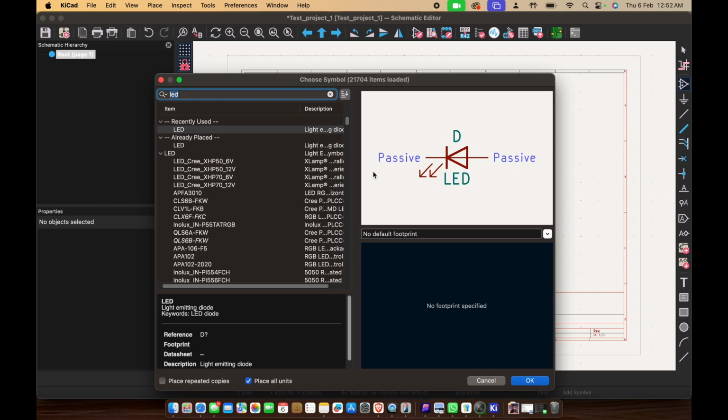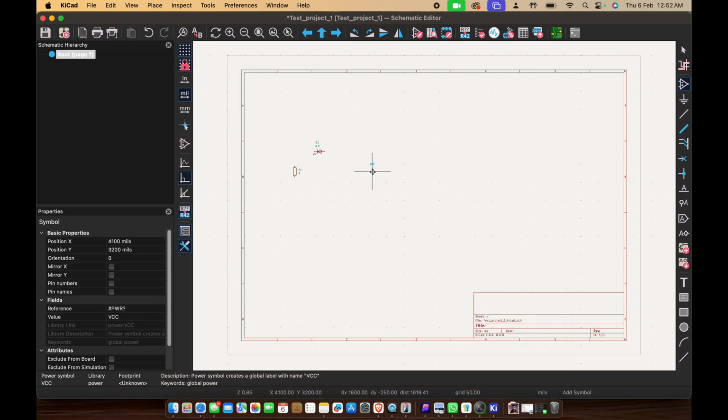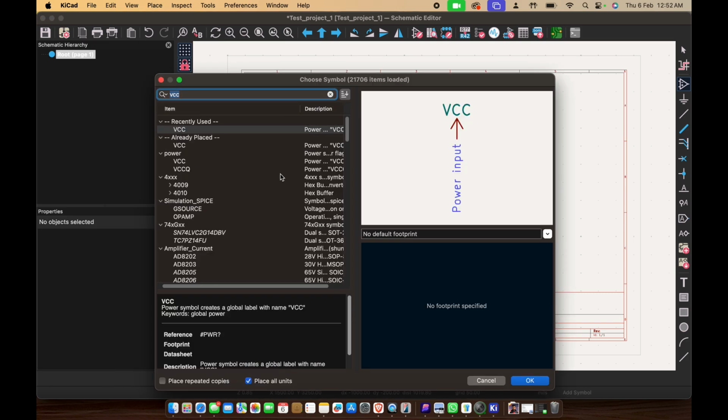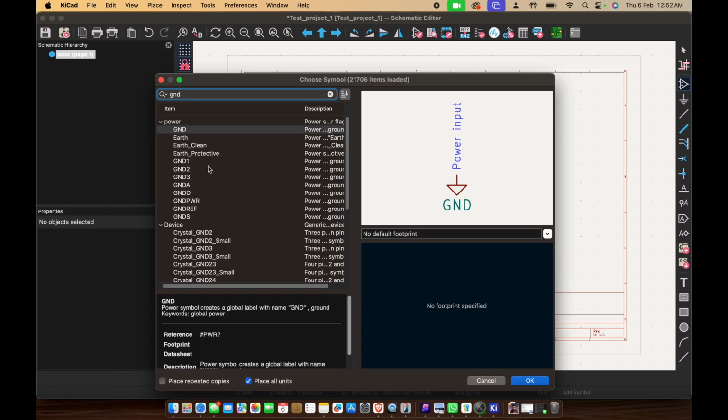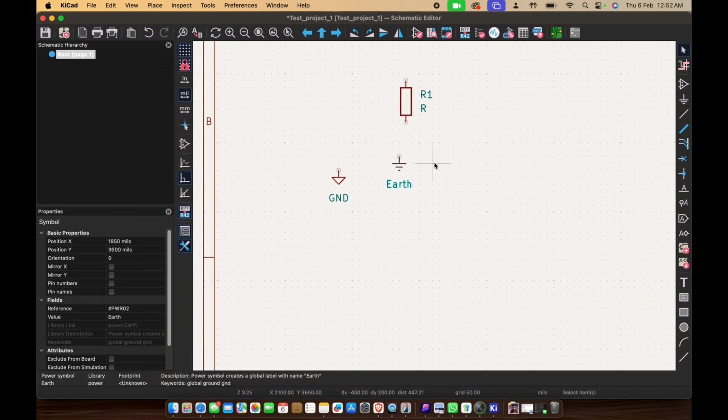OK, press A, VCC. So let's keep VCC here. Then again press A, G and G. Let me zoom in a bit.